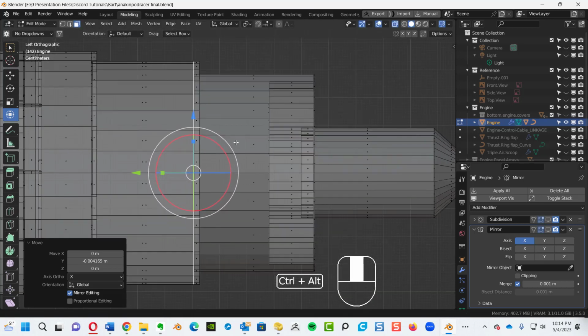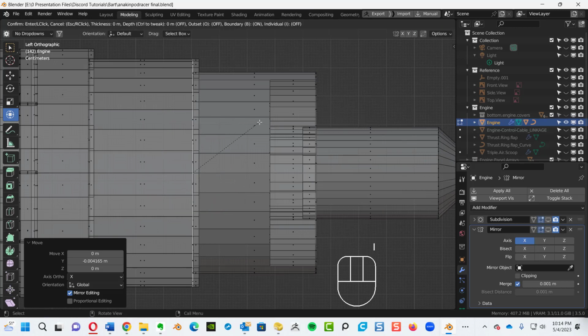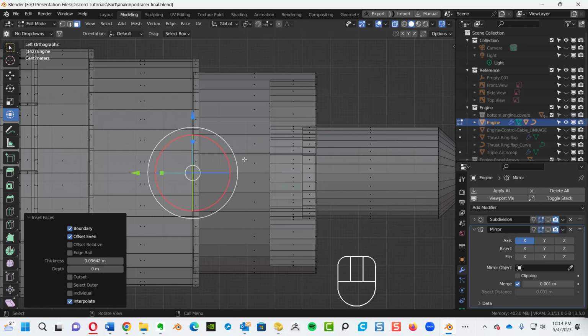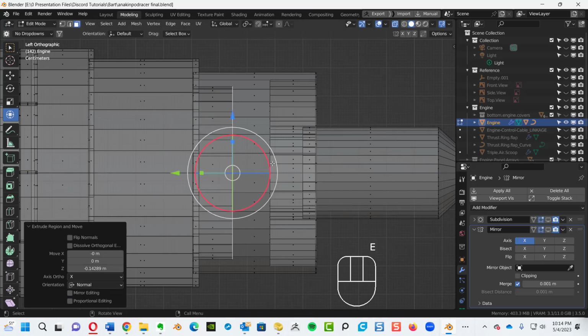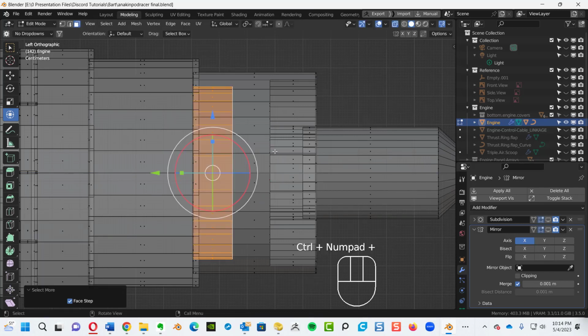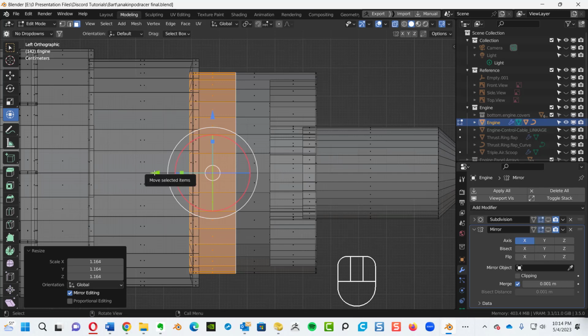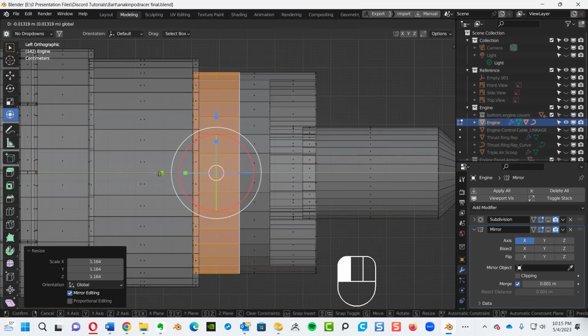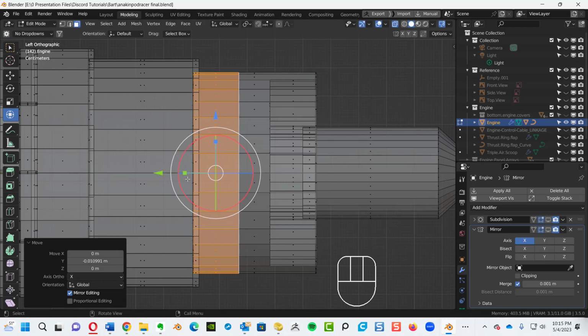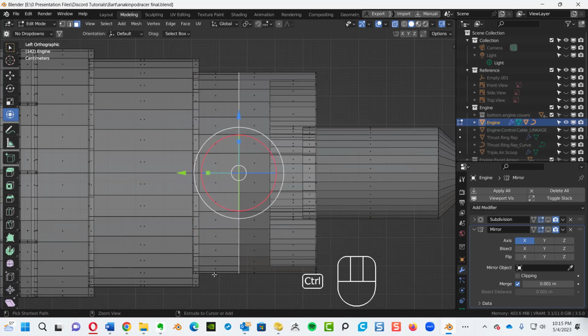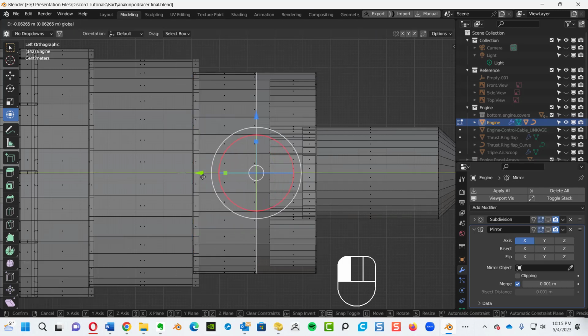Okay, so another I to extrude it in. Okay, and E to pull it out. Oop, way too small, huh? So Control plus, bring it on back, S key. See, just to match this here, and then use my transform just to make sure those edges back here are going to be flush, which they are now. Alright, Control, deselect those, pull it on out.